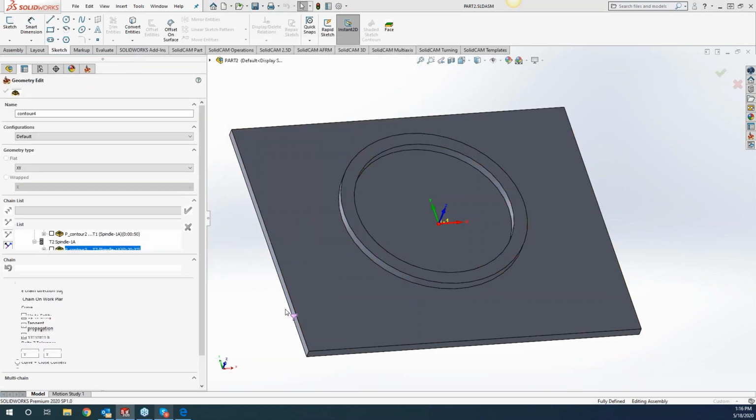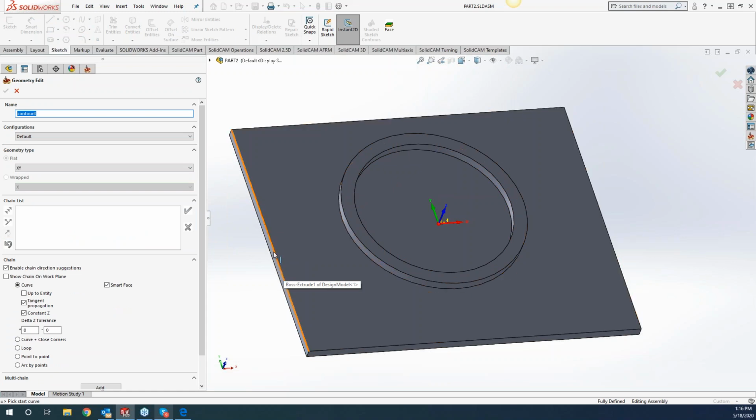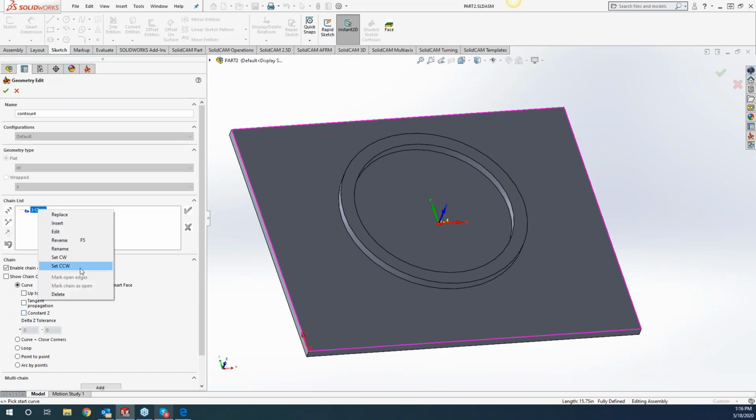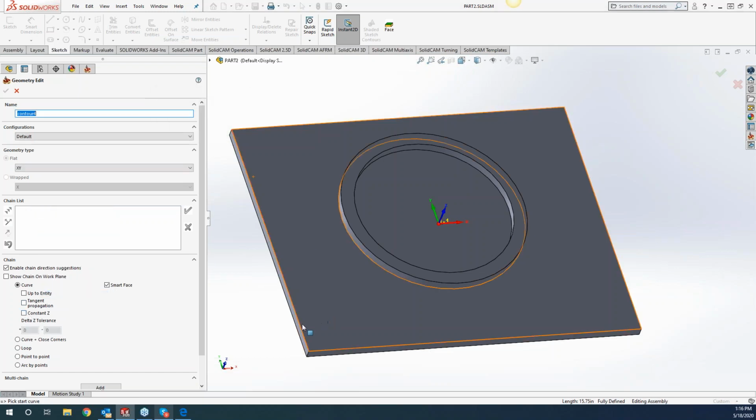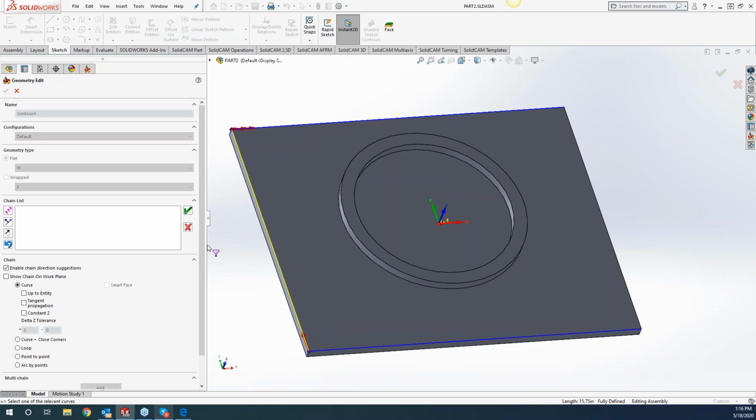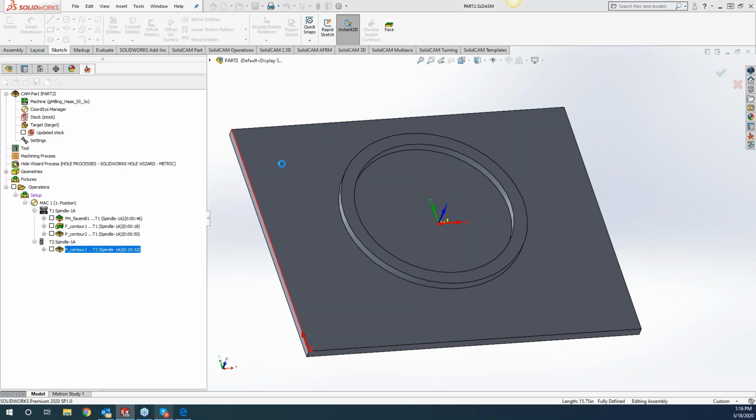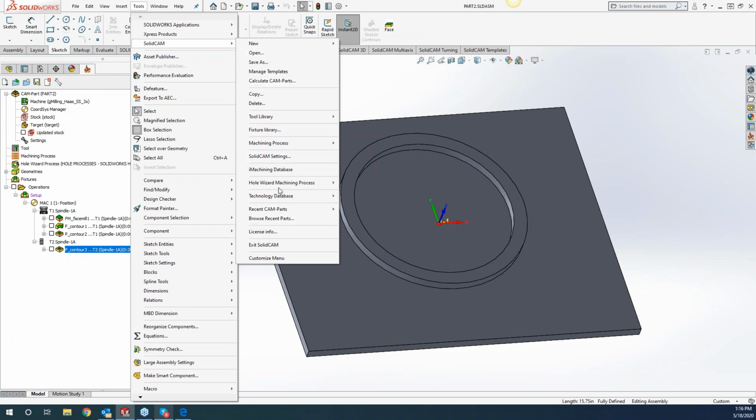And let's say all I want to do is just machine off, do a profile cut along here. Well, so I go click that profile and the chain wraps all the way around for me because these are turned on by default right here. Okay. So usually what you would have to do is uncheck these, delete this chain. And now when I go to grab that chain, I can accept that right from there, and it's not going to auto wrap it for me. So to change that up, that's right where I was just showing you.